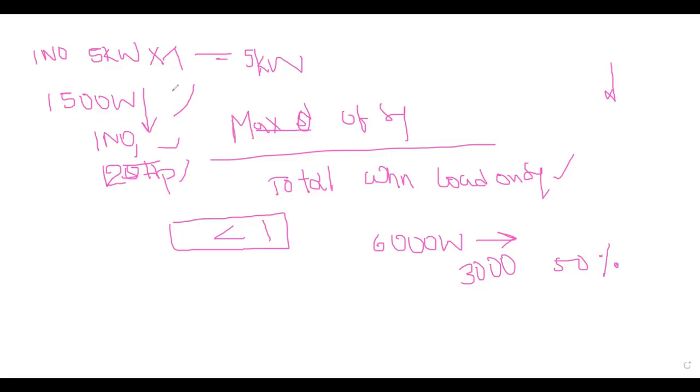The diversity factor into this interval gives me the demand factor of that receptacle, which is nearly, suppose, 0.1, 0.2. The diversity factor for the receptacle is generally 0.1. So I multiply 1500 by 0.1, which gives me some value. In any case, I am multiplying with some factor, which is a diversity factor.